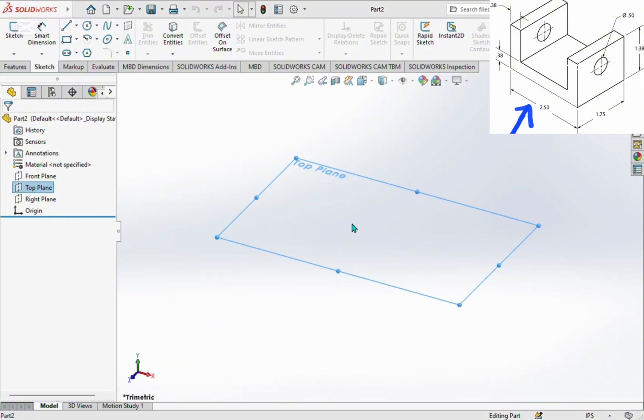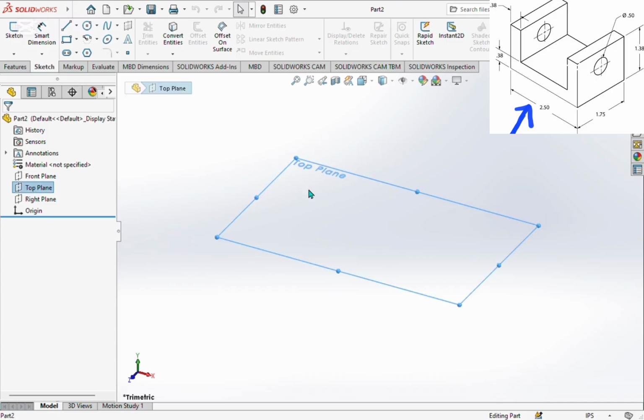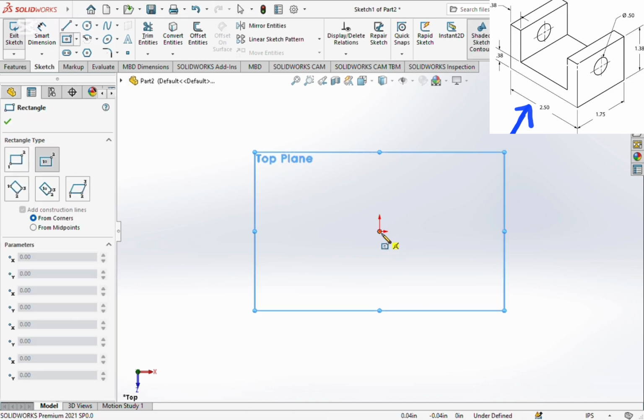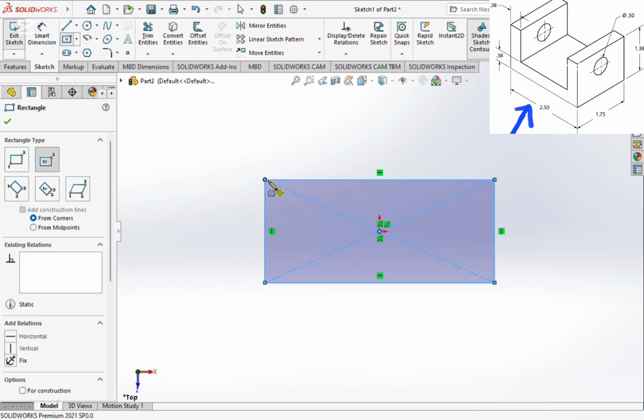If I start with the top plane, I'm going to right click. When I right click, I will select a triangular shape. It will form a triangular shape, then an arrow will point upward. When I do that, it will make this stuff come out. Then I will click my rectangle command, which I did over there. Center rectangle, not corner, center rectangle at that sketch there.